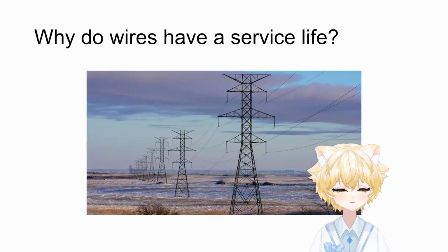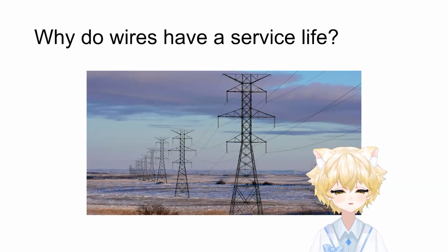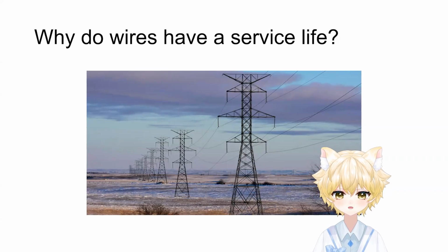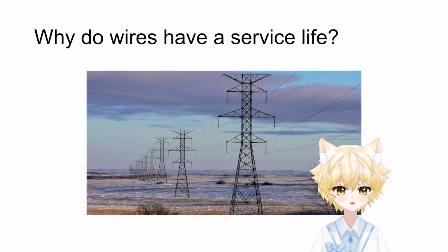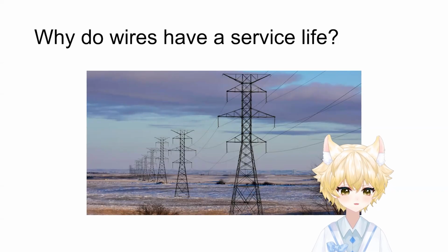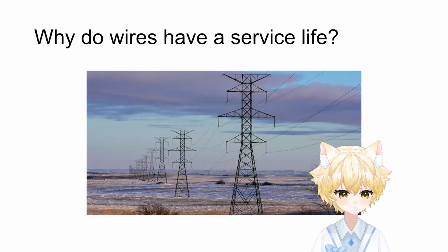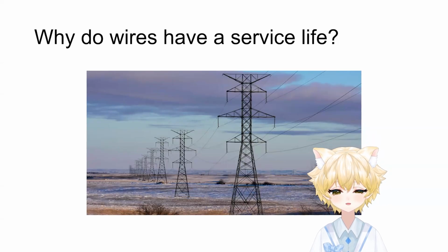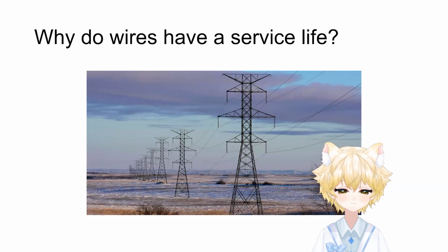So why do these transmission wires have a service life? Why do utility companies have to go out and replace them every 30 or 40 years? They aren't necessarily rusting away, right? So what is happening to them? The answer is a phenomenon called creep.